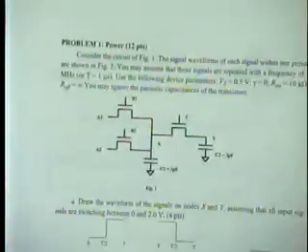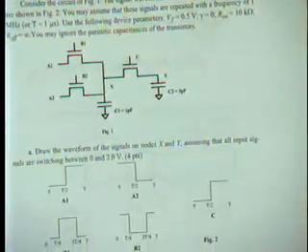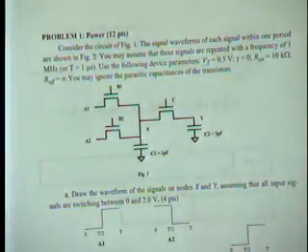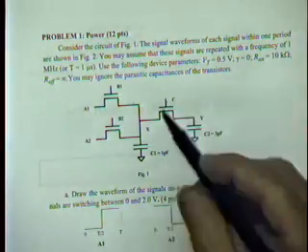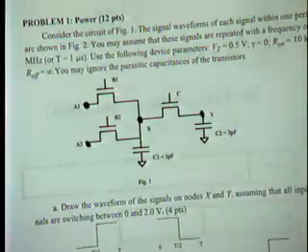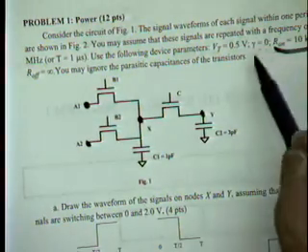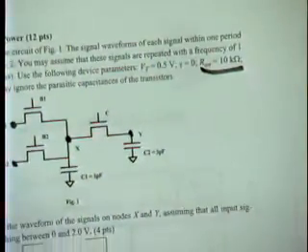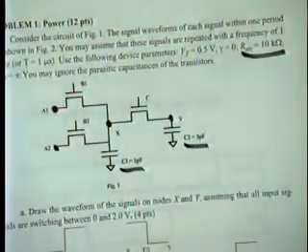This is an exam from the spring of 2003 that we look at. What we show in this particular case is a pass transistor network with various values of the inputs. And we have a certain on resistance. We assume that's an ideal transistor with a VT equal to 0.5, no leakage in the device, and we have given some capacitive values. Okay?